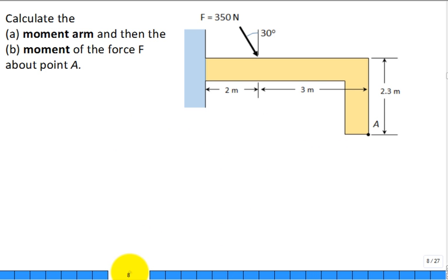All right, how would we calculate this? Maybe in the interest of time, I sketch this out and don't do it numerically. How would you calculate the moment arm for this force, as shown, around this point, as shown? Should I just talk through it? All right, let's just talk through it. There's the point of application of the force on my object. Then I put a line that's the line of application of that force, and it goes on a long way, right?